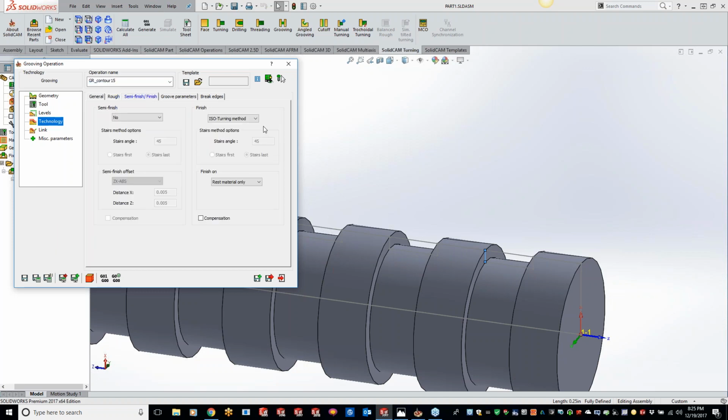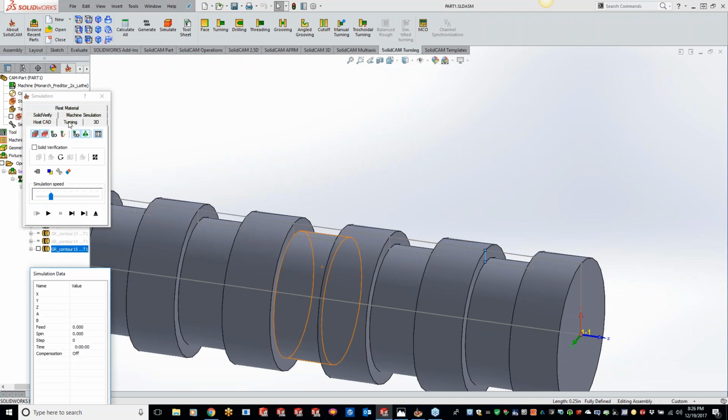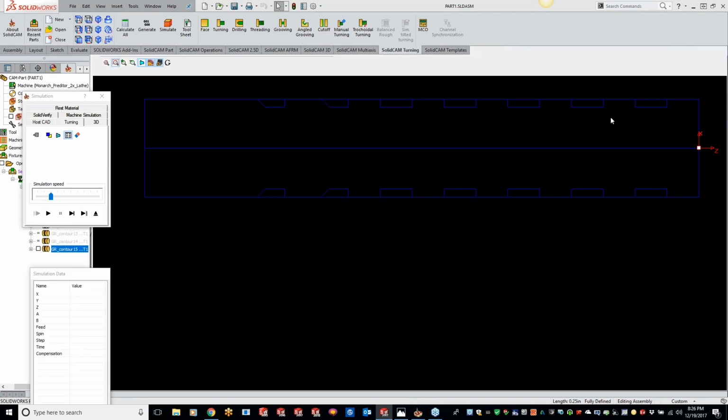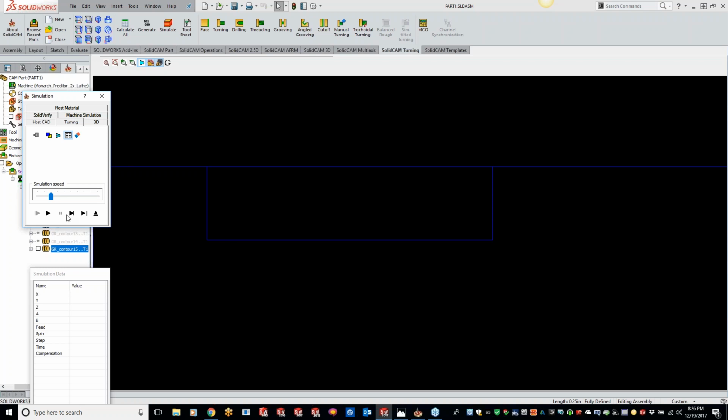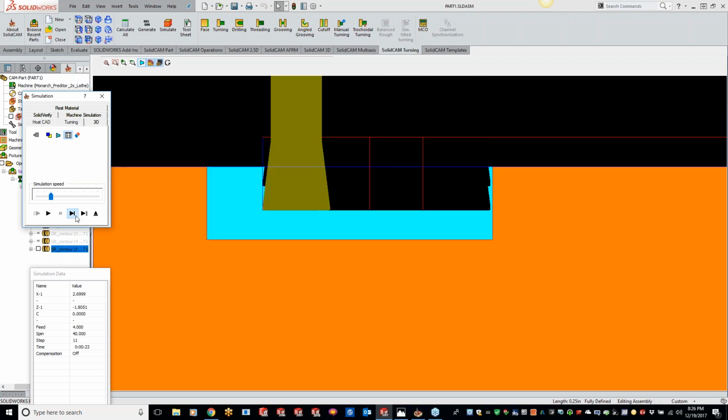Like all of our turning operations, there are a couple different selections in here, depending on what you pick and depending on the tool you're using. So we'll start off with the top turning groove method, starting at center and working its way out. Let's do a save and calculate. I'll save the rambling and just show you what it does here. Okay, I get this roughed out.